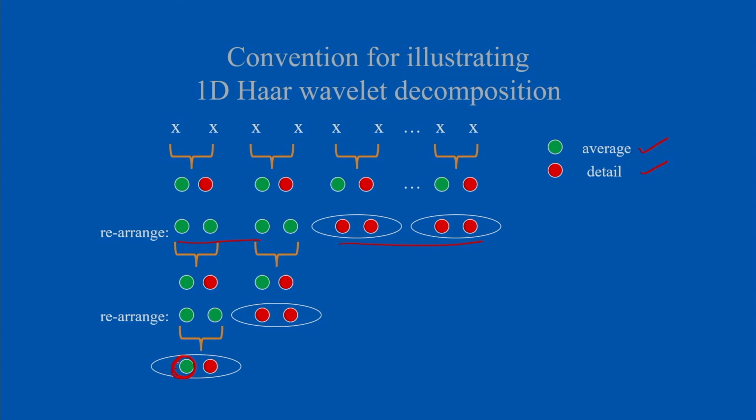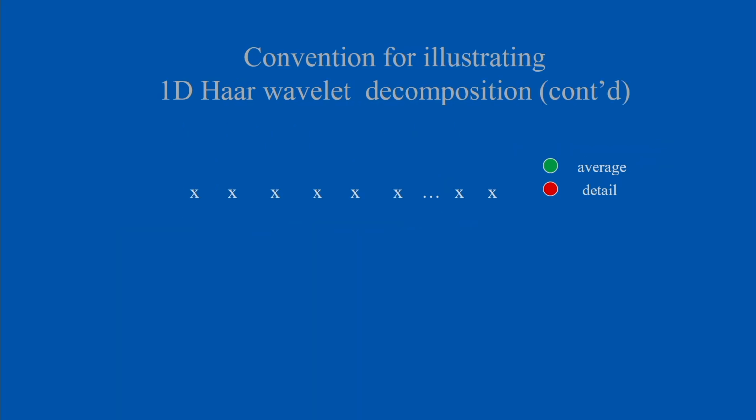You can see this is the approximate component, and this red one is nothing but the detail information. So like this I can do the decomposition by using the Haar wavelet. The Haar wavelet can be used for determining the approximate value and the detail coefficients. Here I am considering 1D Haar wavelet decomposition, and I will be getting the final array like this.